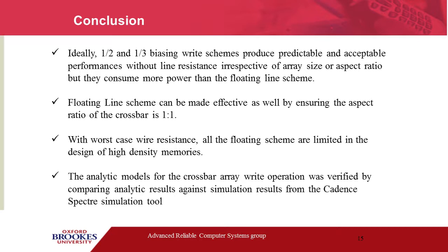I also showed that with worst case wire resistance, all the write schemes are limited in the design of high density memories because line resistance can always trigger write failure in larger arrays. So for the purpose of this work, the analytic models for the crossbar array that we presented were all verified by comparing our analytical results against simulation results using the Cadence Spectre simulation tool.